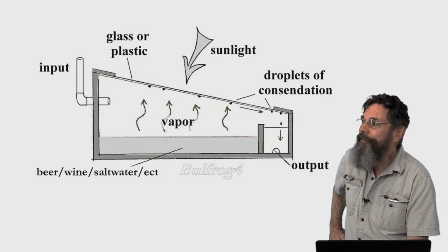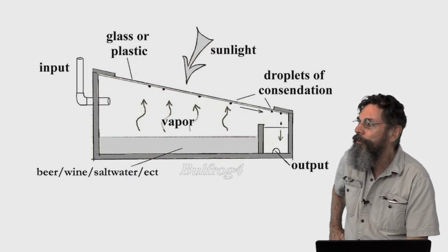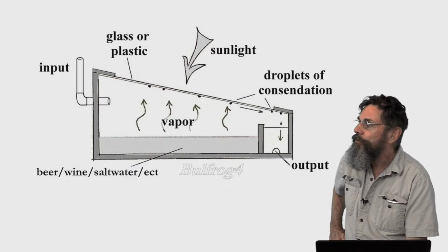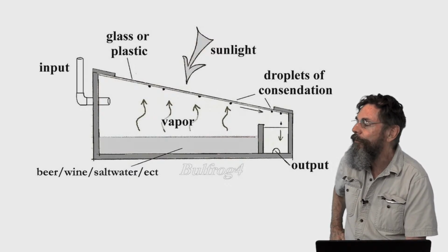Not the ideal angle for solar collection, but if it was too much more tilted than that, as I'll show you in the next slide, as I discovered some years ago, when we were doing some other types of solar distillation. If the water falls down too fast from that glazing, it may either drop back into the container, which is just recycling it again, and you want to try to collect it, not let it fall back, or it may run down too fast and overflow the collector.